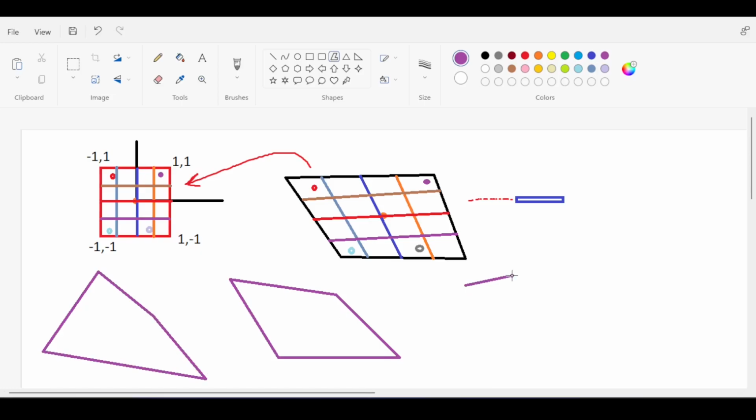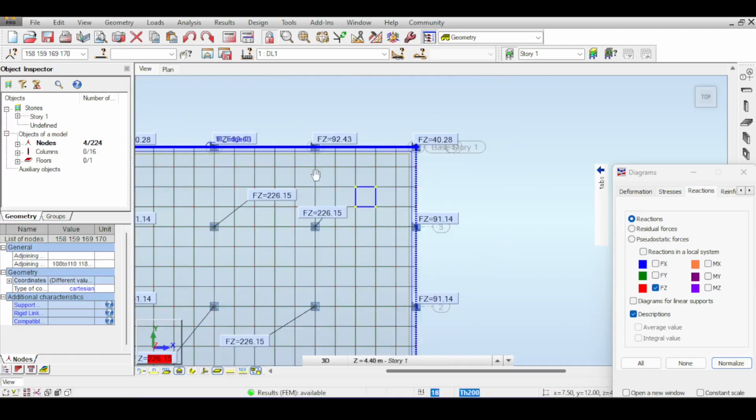And even if you have this kind of element, where you have this sort of stuff happening, this is of course unacceptable. This will even fail the calculation for an element because you have negative scalings. All those elements, the more rectangular they are, the better they are for the isoparametric formulation. Now, will you always be able to do this? The answer is no. For most cases, you will not be able to get perfectly rectangular elements, and Autodesk Robot will try its best. And that's why I love Autodesk Robot, because it has a very sophisticated measure.